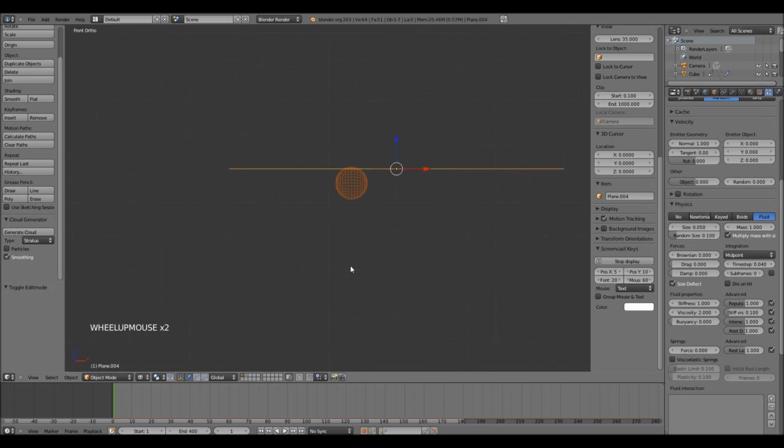When the size deflect is selected, Blender will recognize the shape and the size of the duplicate object. If we did not set the size deflect, Blender would treat those spheres as points, which would give some strange results. When those particles collide with themselves, with our rotating object or the floor, they would not look like spheres on the surface.